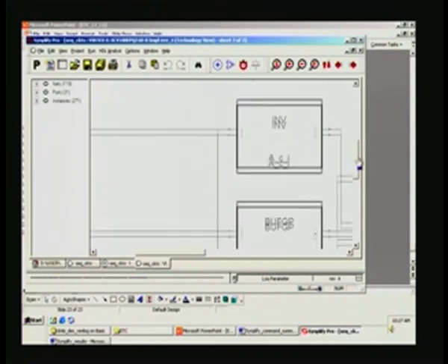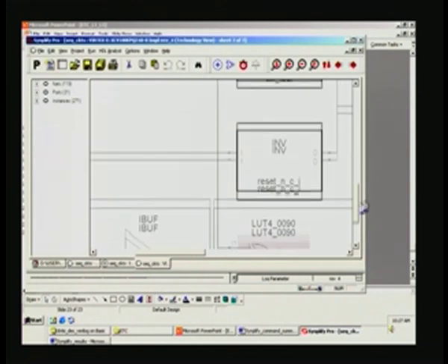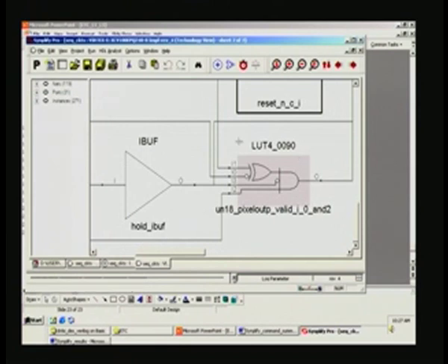So one inverter and all that buffers. So nothing more other than all these primitive cells that we have already explained. So 4 input LUT. You can just see 1, 2, 3, 4 inputs are there. So actual logic realized using the 4 input truth table, it's basically AND, and is what you see here, and with an inverter here.